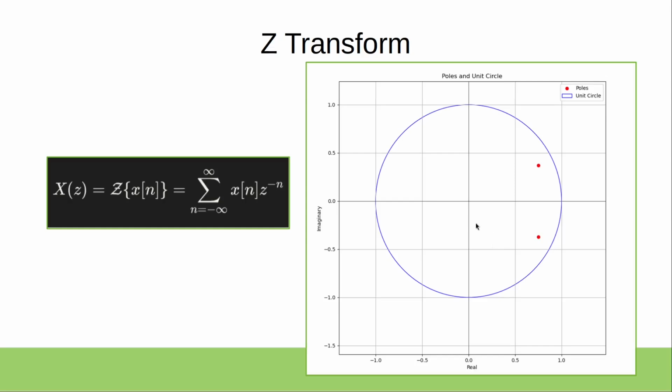And that's basically the majority part that you need to understand. The reason why we employ the Z transform is that the system dynamics actually change depending on the discretization. Usually when the discretization is very small, in the sense that the sampling rate is very high, it's almost an emulation of continuous time, so you won't really see a big difference between the Z transform and the Laplace transform.